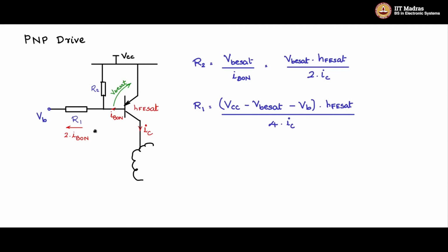So this is exactly the dual of the NPN drive, and in many cases, many complex drives are built from these two drives. NPN, PNP they complement each other, and many stages can be achieved by this NPN, PNP combination. We will of course have a look at these complementary drives later.